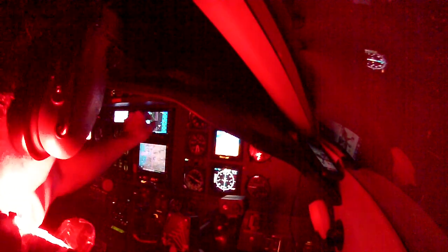124.0. Okay. So you've got to go to the point, pass it, and then come back, try to look for it. That's right. So it's good to have the DME, distance measuring equipment, so it's perfect over there. Well, if you're doing an ADF approach, which is an NDB approach, that's the only way for you to do the NDB. Because this is your primary navigation. You can back it up with the Garmin, but this is your primary ADF. Oh, but it's good to have the distance measuring equipment so you know how far you are from the station. Absolutely, you can use the Garmin to back it up.